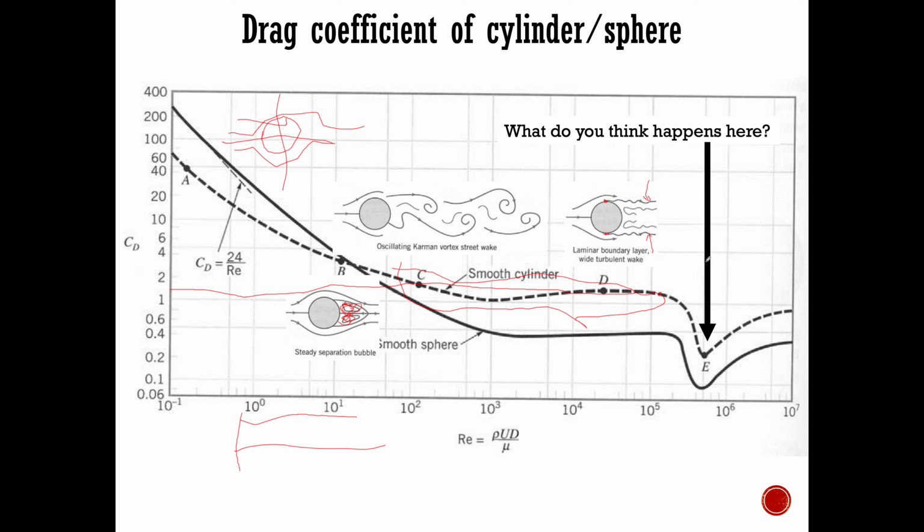Now, if you keep increasing the Reynolds number, what's going to happen is that the separation point is going to get pushed towards the back of the cylinder, which decreases the thickness of the wake, which decreases the momentum deficit, and that will reduce your drag, right? Which is pretty cool, and this is basically called the supercritical regime or supercritical Reynolds number, where the transition from laminar to turbulent happens much later on the surface of the cylinder. Right? I hope you found this interesting.